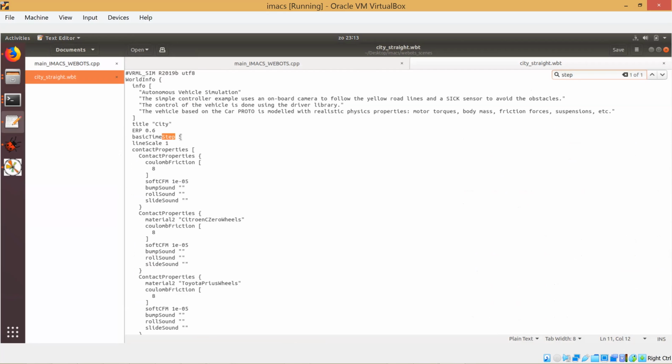You can increase it or decrease it, but make sure that it's in multiples of your delay or sampling period, because if it is not, then you would end up in a mismatch. For instance, if I have my delay to be 8 milliseconds, but the simulator will only stop at 5, 10, 15, and so on, the 8 you would have to round up to 10. So if you design for 8, then there would be a mismatch.